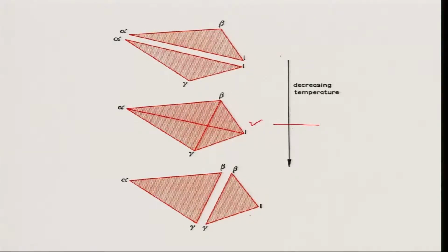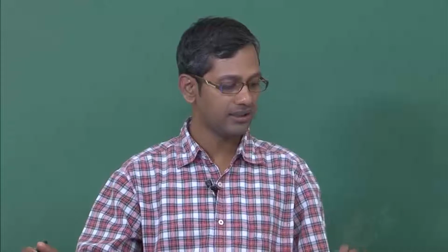If you look properly, liquid plus alpha going to beta is a monovariant peritectic reaction in a ternary system. Ternary means 3 components, and 3 phases are present. So, C minus P plus 1, C is 3, P is 3, they cancel and 1 will remain. So, degrees of freedom will be 1. Now, in this case, liquid reacts with some primary alpha and forms the beta, and this reaction, that is formation of beta by reaction between liquid and alpha, continues till it reaches the ternary quasi-peritectic plane.